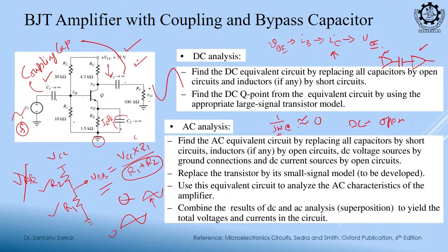Now, if we use this capacitance, then what is it doing? It is bypassing this IE-RE value, right. Bypassing means, suppose you have a longer path and you have a shortcut path, and you will take the shortcut path to reach quickly, right. So, this path bypasses this IE-RE drop, and as if there is no drop, ground, right, 0, this emitter potential is at 0.